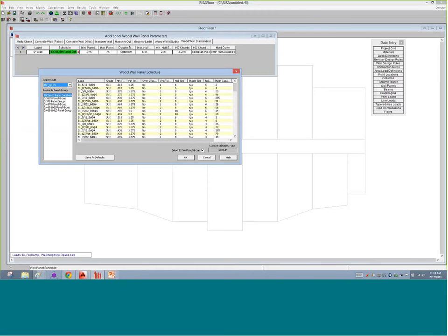But what you do see is that you have a long list of different size panels. And the information on that label should tell you everything you need to know, whether it's structural grade, 5/16-inch thickness, 6 penny nails at 6 inches. That's pretty much the name gives you everything you need to know about what that panel is. The 2 in parentheses tells us if it's double-sided. You've got all sorts of information listed here.